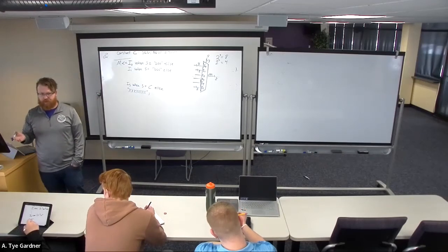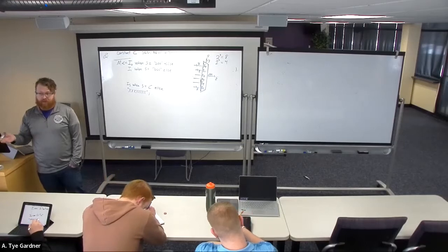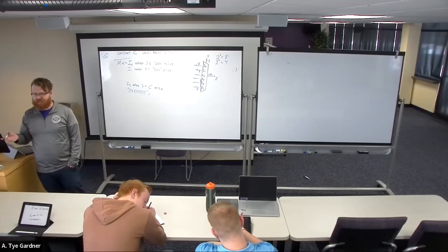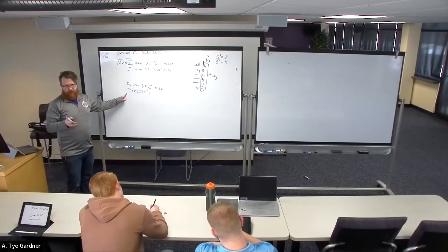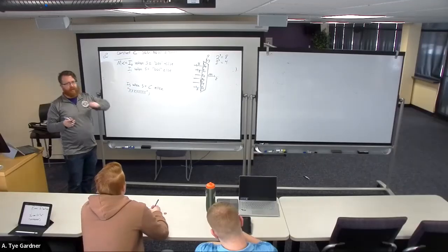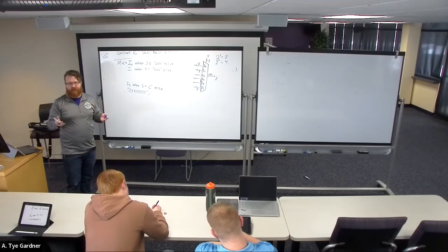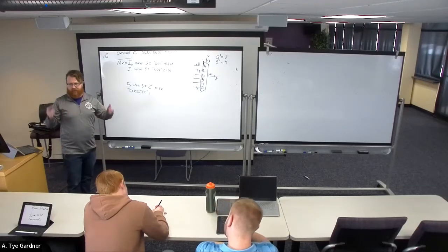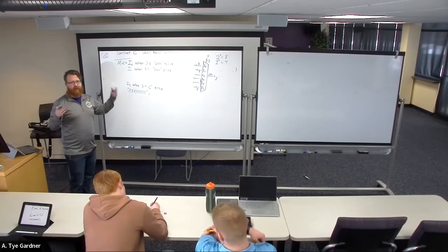It usually means dual driven, but here it's just saying my output should be X's if I give it a bad input. If a mux is selecting something that it's not supposed to, do X's. This is helpful if you actually don't connect the select signal. That way, when select is U or undefined, my output is X, and now I know I connected my select wrong. It's a really good tool to try and identify what's happened.